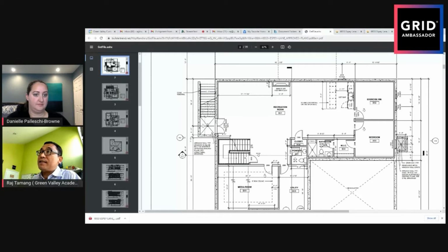So what we do, let's say this is a 5 foot double door, 60 inch. You have to remember that the door has to be nailed somewhere. I won't be able to nail directly to the concrete wall. So on either side of the opening and at the top header, you have to embed 2x6, let's say 2x6 pressure treated.